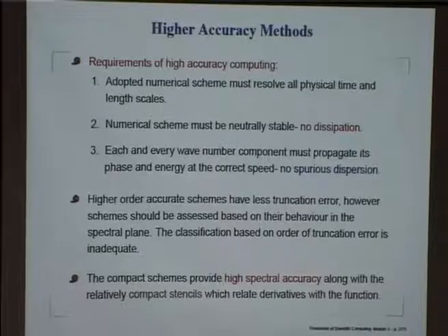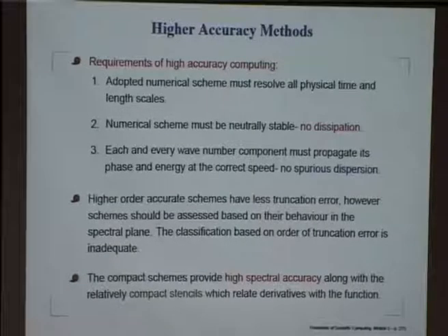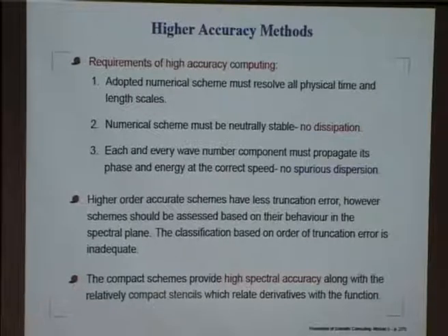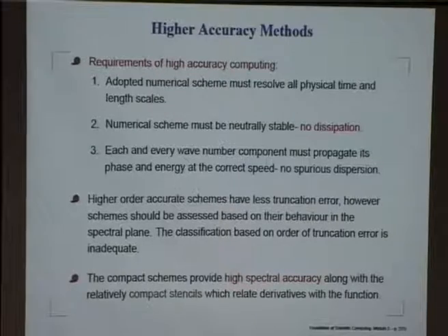you have to resolve all those wave numbers, and at high wave numbers, as we have seen, we can invoke dispersion error. We often have this tendency, in the absence of a standard solution, to view these spurious solutions as representing turbulence, and that is one of the diseases of modern day, and we should resist doing that. So the third point is nonetheless still very important. We need to talk about no spurious dispersion.